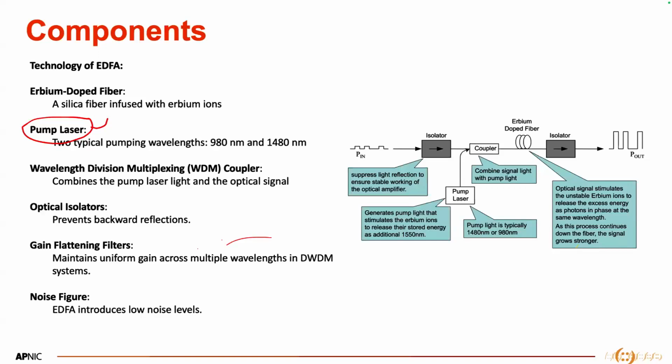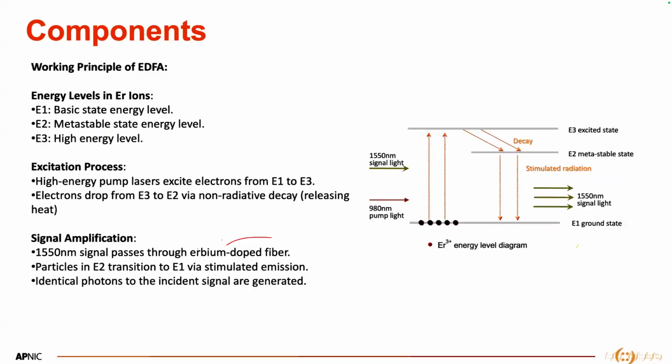So you can ask why it is like that. Why are we using a different wavelength? You can ask that the pump light is 980 nanometer and the incoming light is from C band, right? So they are different. Why? Because first of all, we are trying to pump lasers. So 980 means we are using the laser or wavelengths for the multi-mode supported version, right?